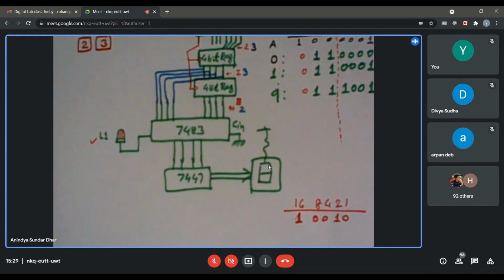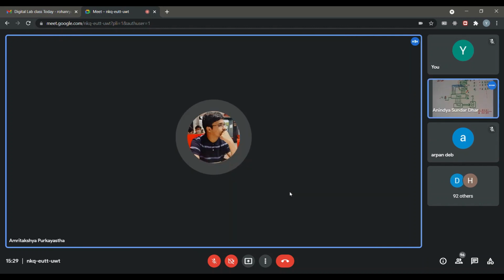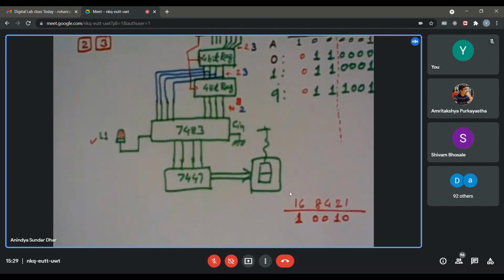And by any chance, are you aware how to convert from binary into BCD form? Like you mean the addition result? So you need to add 6, whenever there is either a carry or it is beyond that 9 value. So in this case, if you add 6, it will become 8. Okay. So the first digit you will display in another 7-segment display, and this 2 plus 6, which will be 8, you will be able to display in another one. So maybe that will be the next experiment. If some of you wish, you can actually go ahead a little bit with that.